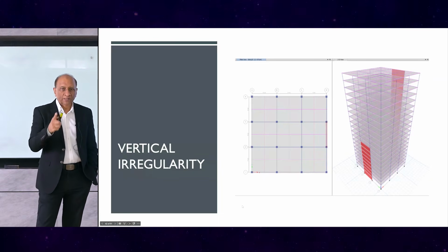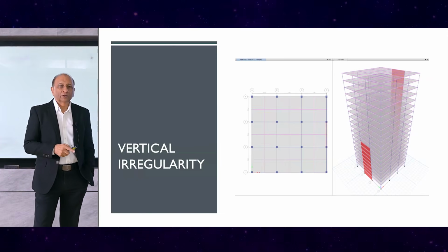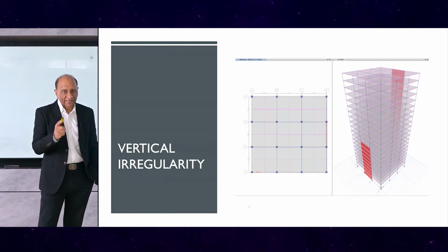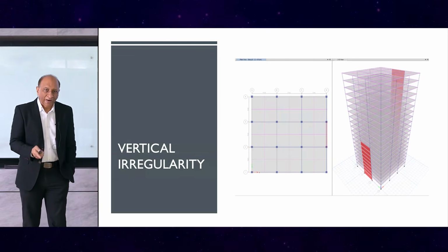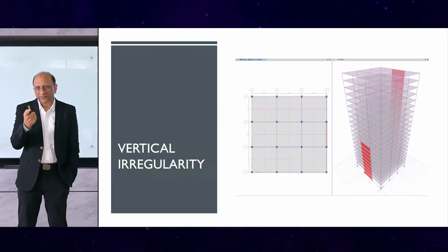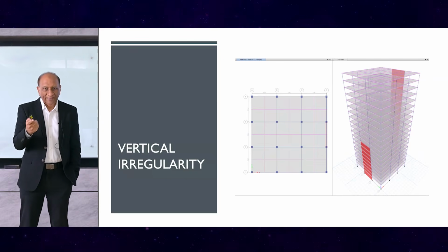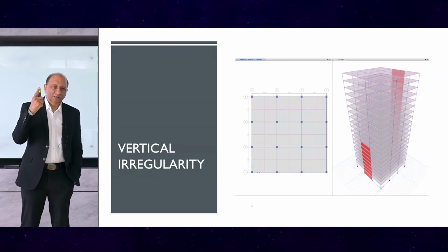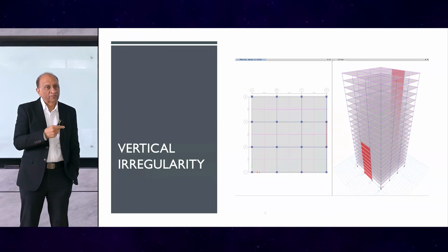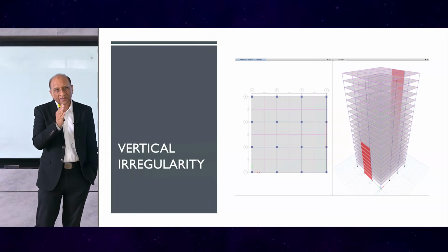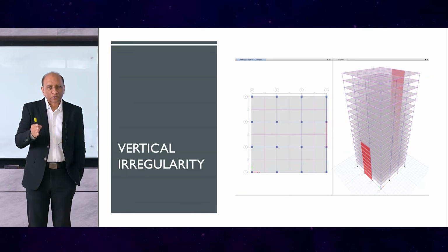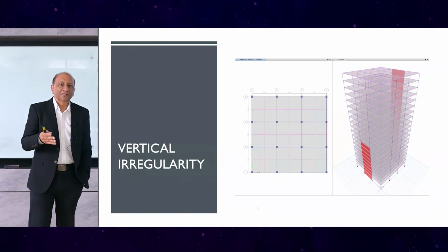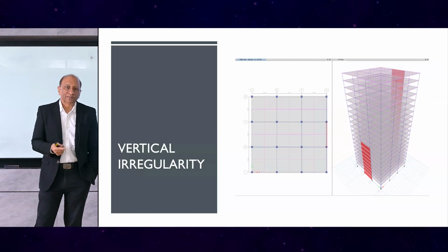We put two walls and we put one wall shorter than the other. This will create a highly complex dynamic response because now part of the structure up to the 8th floor is symmetrical in y direction, but it's not symmetrical above that, so it will now shift the vertical stiffness center from the center to the right and so on. So now we are creating a highly irregular structure.